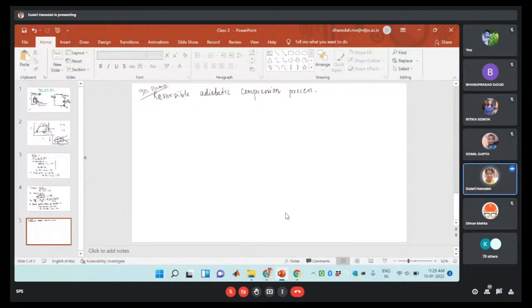This pump will handle liquid water, which is incompressible. So in this case, your density or specific volume will change in a small amount with the increase of pressure. The pressure will increase due to the compression, but the change of density and specific volume is much smaller than the increase of pressure.